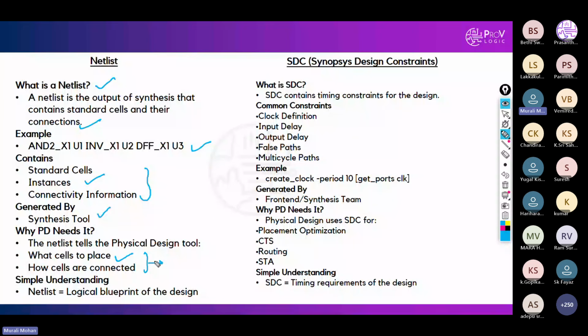It consists of cell width, that means this is a set row, so this is where it's placed here. What is this width? Physical information. Next, what height? The chip also has input pins, meaning what is the exact location. Next, is there any routing blockage for this particular standard cell? And what is the metal information? So which metal was the particular pin built with? That means this pin was made using which metal layer. This kind of physical information is present in this particular LEF file.